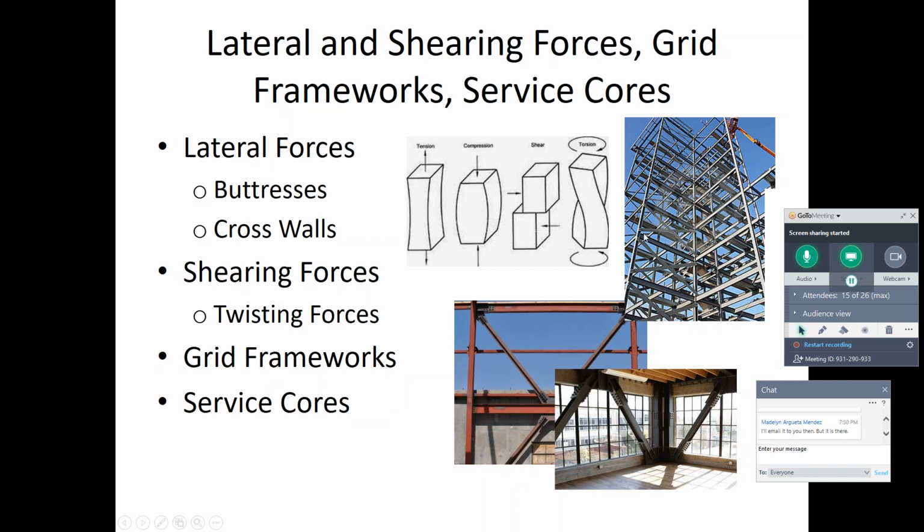And then up here, I just have an example of the inner grid work that's created by our steel framing, from which everything can be placed for the overall interior of the building. Because we have frames like this, we can get to those larger expanses where we don't have to use light wood construction, and we can have big open rectangles without so many load-bearing walls in between because of the strength of those I-beams and post supports from the steel framing and the grid work.